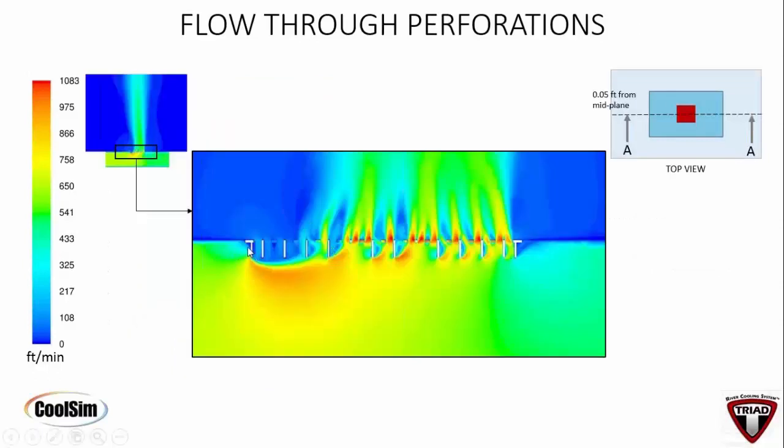And what's happening under the floor right here, this is the same exact geometry that we brought in mesh, and you see now under flow conditions, again, flow moving from left to right. What it does is it hits this leading edge right here, and the flow separates. It goes way out and doesn't come back until in this area here. So here's exactly, Gary, some of the readings you were seeing. There's your low pressure reading with your velometer, there's your high velocity region right there. And here's your reverse right here.